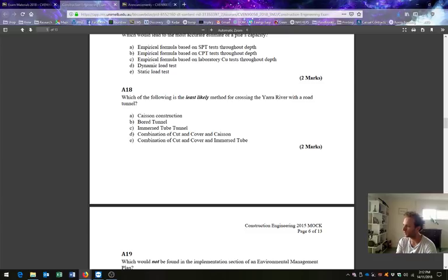Cool. So we're moving down now to Fraser. Yep, great. When multiple boom lengths are appropriate for the mass and radius, what justifications are there for selecting one boom length over another? Typically, if you haven't got height requirements, so if you're not lifting high up on a structure, you keep your boom shorter. You pick your shorter boom length that'll do the lift. Takes less time to extend, and typically you'll have more capacity from your crane as well.